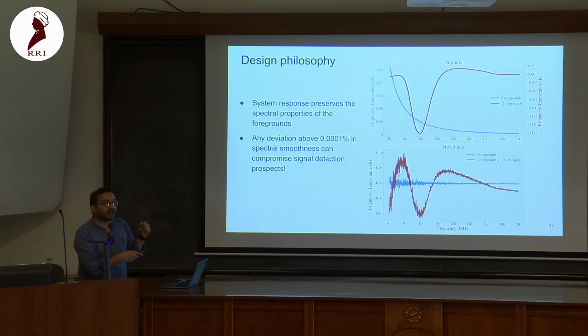Yeah. So when you say there is impedance mismatch, two questions. First of all, why does it happen? And secondly, how much mismatch is there? Right. So I'll probably touch upon this later when I talk about the receiver and subsystems. It's mostly because of our antenna response. Other things are fairly matched, but the antenna is very hard to match across a very big frequency bandwidth.